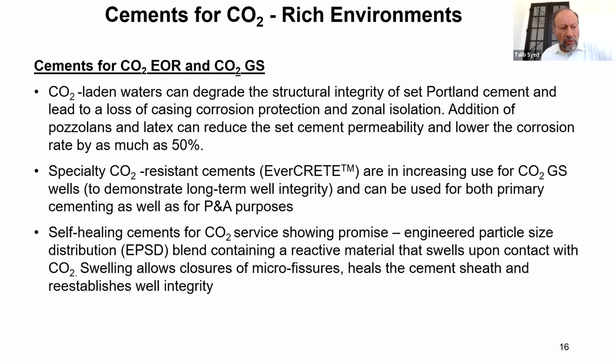Cements for CO2 rich environments, specialty CO2 resistant cements. Evercrete, I think, is a Schlumberger product, and others also have it. And then you have self-healing cements that are showing promise. Basically, the swelling allows the closure of microfissures, heals the cement sheath, and reestablishes well integrity.